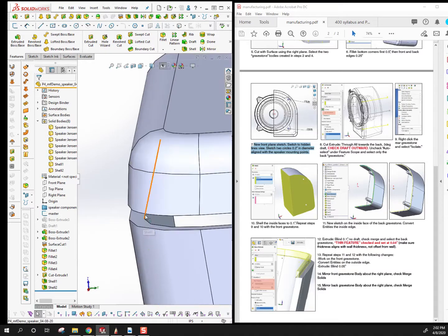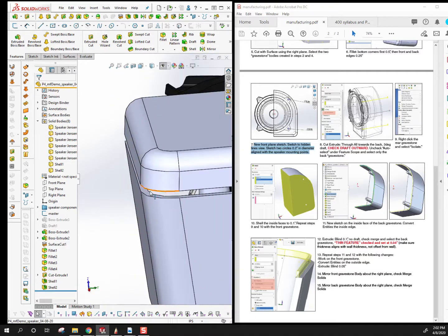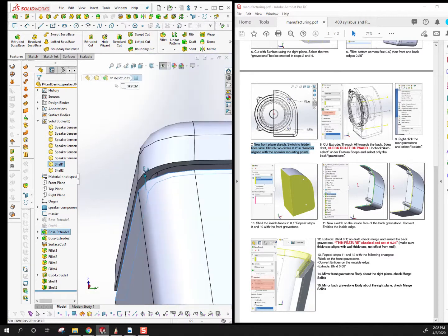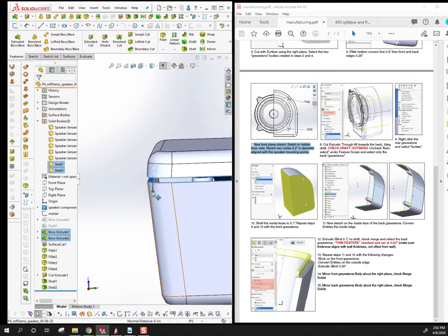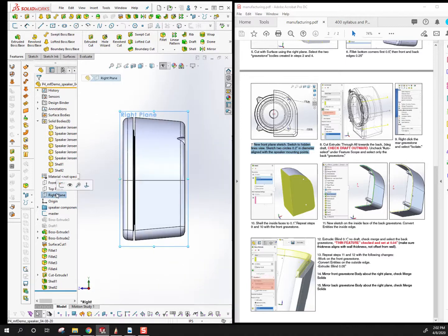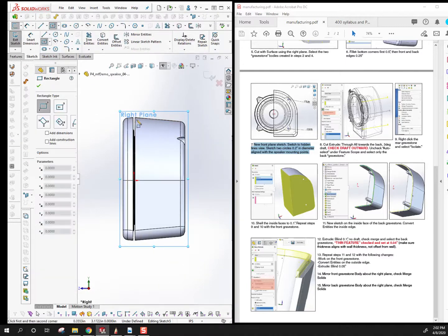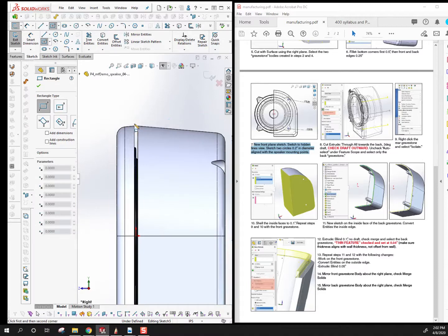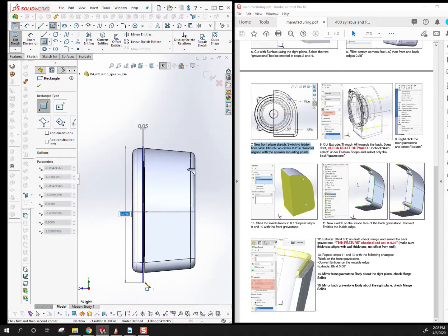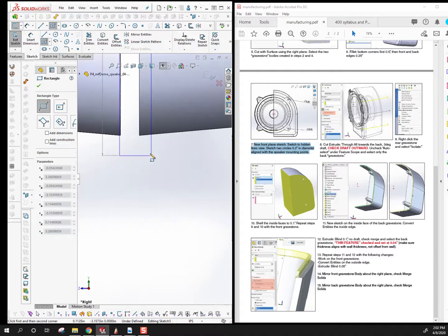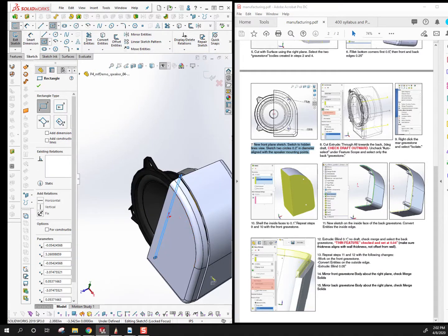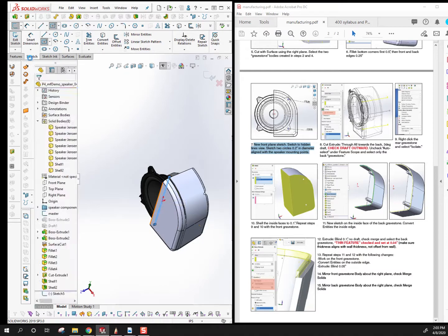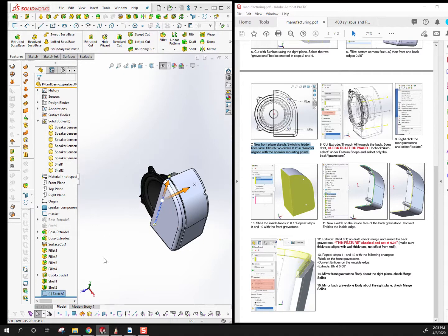For what it's worth, if it is your own concept, this is planning ahead for that part line by doing this offset extrude like this. You could always come in and make this gap here. This is a 0.1 inch gap. You can do this as an extruded cut from the side. I'll show you what that might look like. From a right plane, Alt-S to create the sketch. Imagine that these are touching. You could just simply sketch a rectangle in here that's about that width and just cut through everything to get that gap. Again, if it's your own work in your own concept.